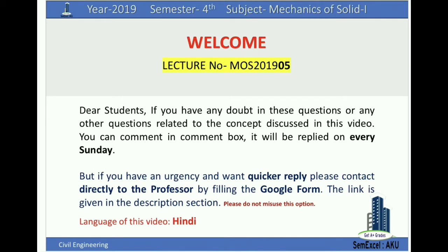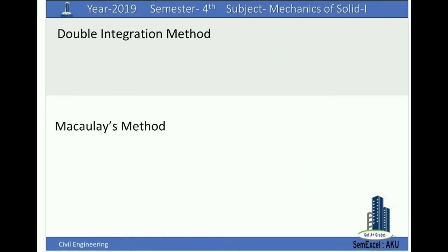So let's start. First is the double integration method. Let us say we have a beam. This is the beam and there is some support conditions and there is some loading on it. At any distance x from the support, let's take out a small piece of length dx.